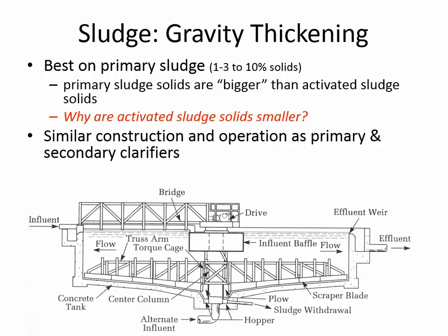So the sludge itself, the mass didn't change. The mass of the solids didn't change. But remember, sludge is two things. It's solids, a little bit of solids, and mostly water. So if we can get rid of some of that water by drying it out, by vacuum separation, by heating it, whatever, if we can remove some of the water, it increases the percentage, and then that means that there's less volume to dispose of.